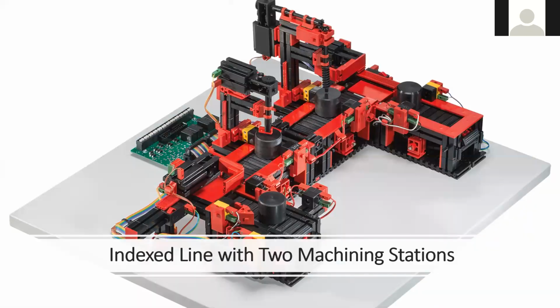The next model is the indexed line with 2 machining stations. This model features a U-shaped conveyor line consisting of a milling and a drilling station and 4 conveyor belt sections. Components on this model include the 4 conveyor belts, as I just mentioned, 8 XS motors, 4 push-button limit switches, 5 photo transistors, and 5 LED light barriers. The dimensions of this model are approximately 19 by 18 by 11 inches, and it has a weight of about 8 pounds.